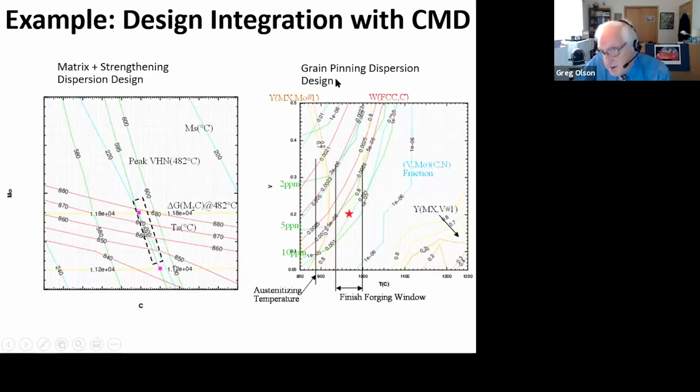So we're constraining these grain refining particles to be soluble at homogenization temperatures, able to precipitate out at forging temperatures, and then maintain a certain phase fraction and size at the final austenitizing temperature of the steel that sets the grain size of the steel. So similarly, we can back up to even earlier stages of processing, specify the deoxidation processes that set the primary inclusions at the multi-micron level that are important to toughness and fatigue resistance. But that graphical strategy is very efficient, and it is the practice that we use at QuesTek and the practice that I teach in my design class.